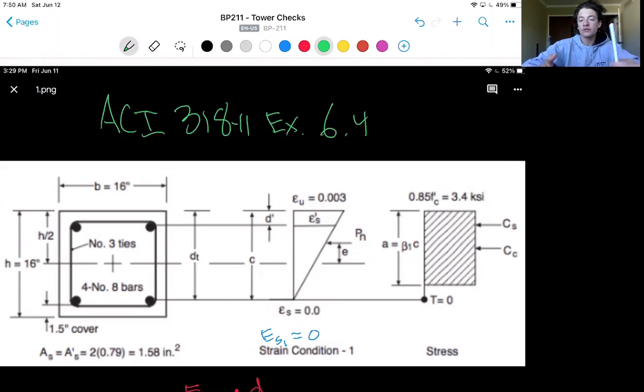At this point, you should have gone through the equations from the previous lecture and set up your Excel spreadsheet. It doesn't have to be Excel, but Excel is what I've used. The spreadsheet should calculate all of the terms all the way through your axial load, axial capacity, and moment capacity. Throughout this video, these 4 conditions will help round out some of the values for that interaction diagram.